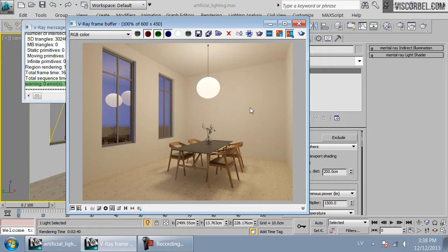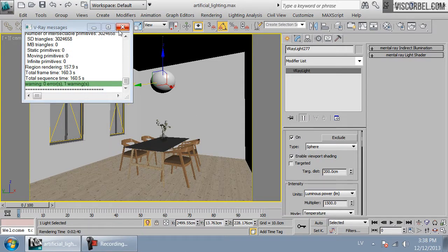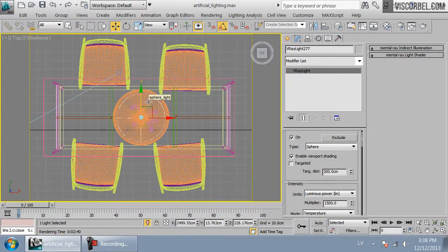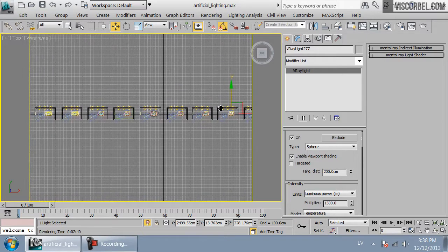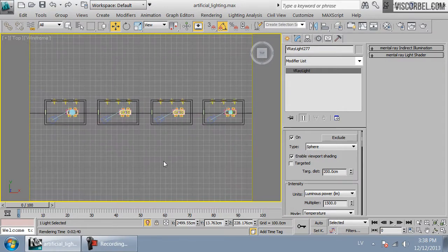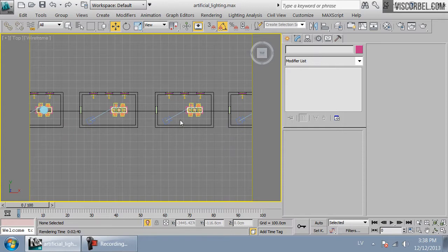So this works the best if you have a completely enclosed bulb. So there are no spots that should be brighter and no spots where you have this direct light. Everything is illuminated by this diffuse large enclosure. Okay, so the V-Ray two-sided material can be used in some other scenarios as well to quickly render lampshades, especially if the lampshade is made from cloth or paper.